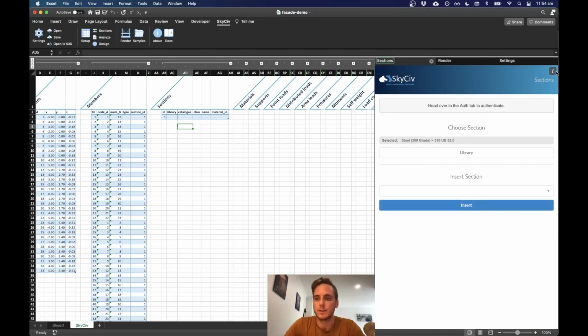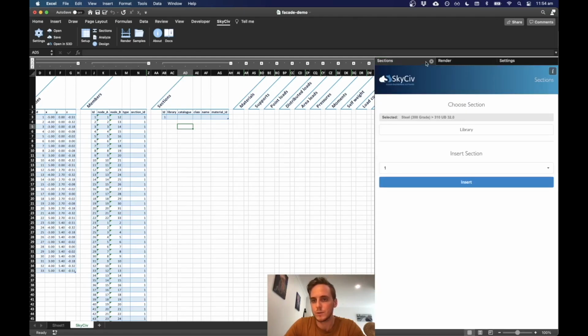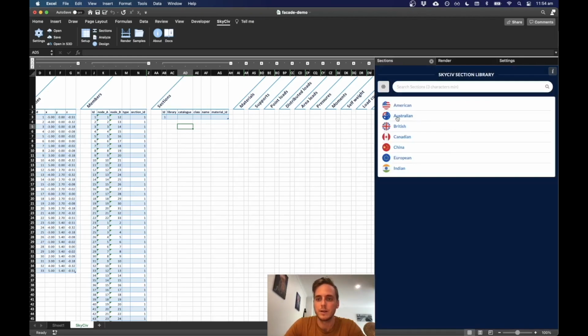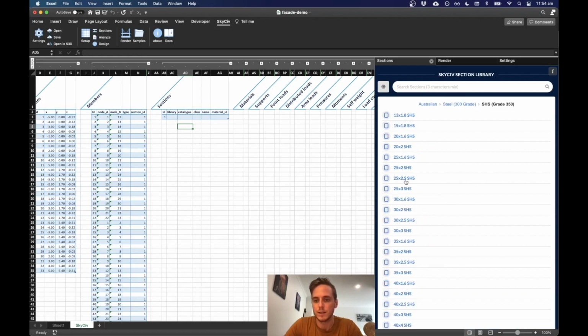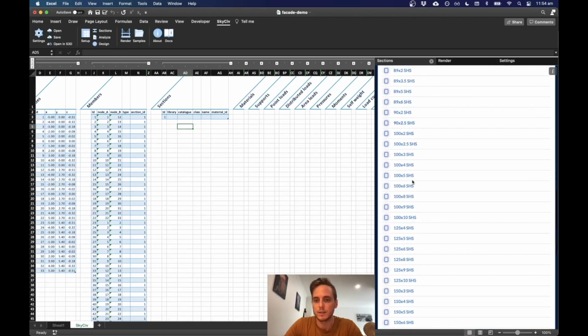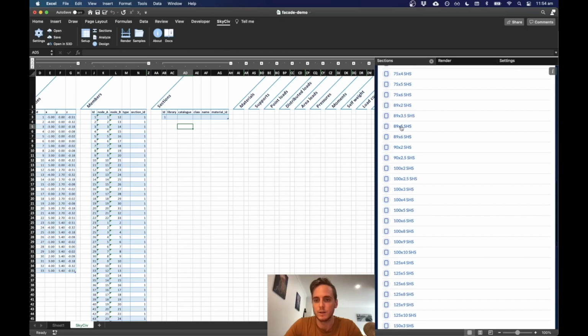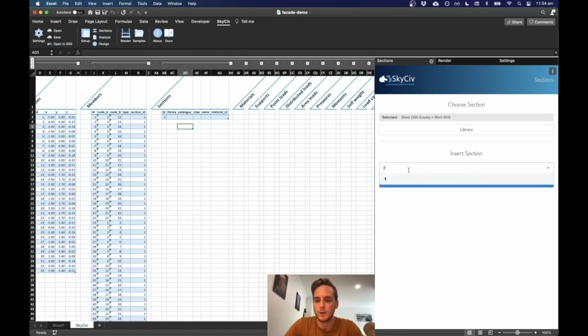So now if we come back over here, we might just need to refresh this. So for me, I can just go to reload, or you can just close this window and reopen it. So now we're back to here, we can go to library. For me, I'm going to go to an Australian section. Steel 300, you can also search up here. We'll go to SHS, and then we can pick an SHS. So we'll go 89 by 5, and we're going to insert it into section 1.